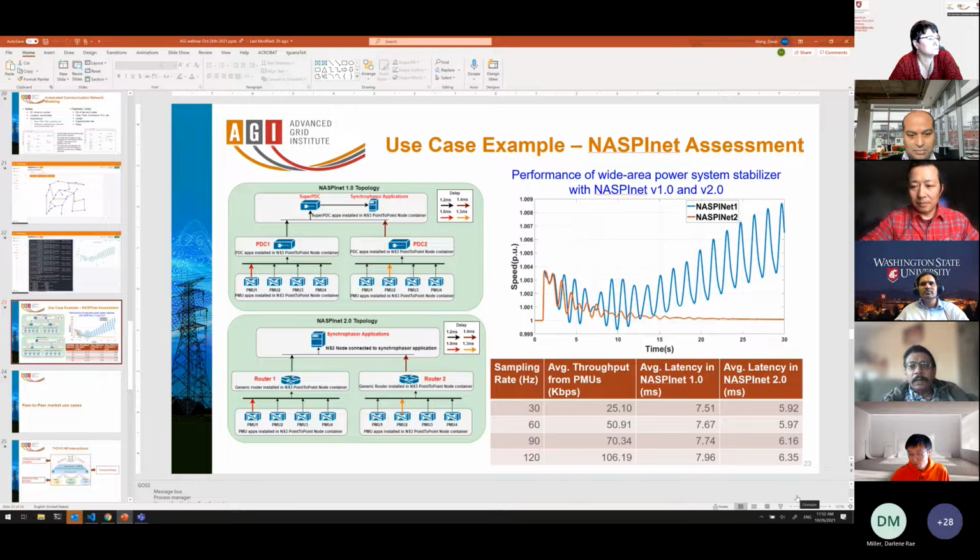I'm puzzled that such a small difference in delay would lead to instability, because a few milliseconds, or in this case less than 2 milliseconds, should translate into a few degrees when we think about stabilizing control in terms of either a phase lead or phase lag or whatever is the stabilizer that you are working with. And that should not make the trajectory change from a stable response to an unstable response unless the controller was designed near the limit, which is not how it is done in reality.